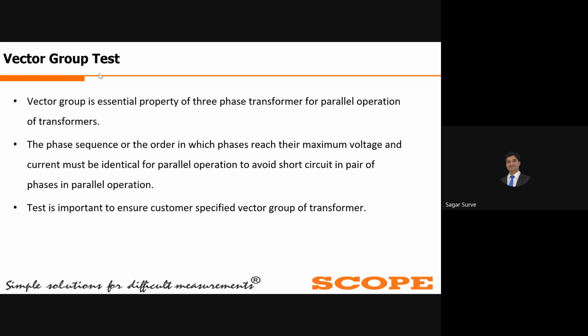And this test is important to ensure the customer-specified vector group of the transformer. Means this test is also conducted in the field. So to identify whether the transformer is as per the required specification of the customer, we need to conduct the vector group test.